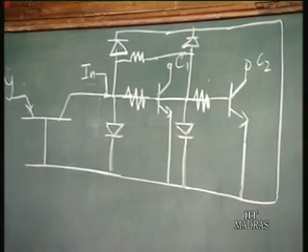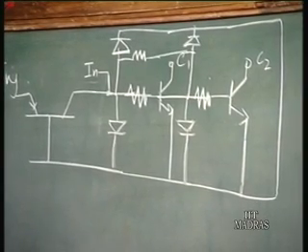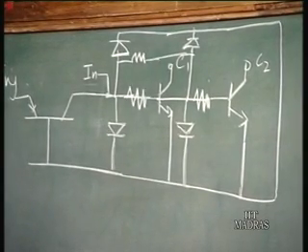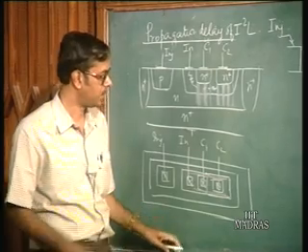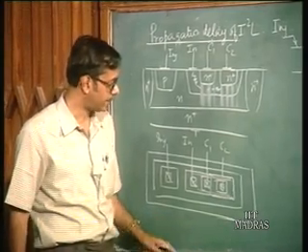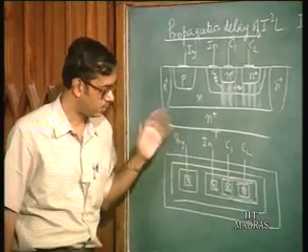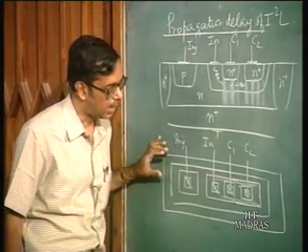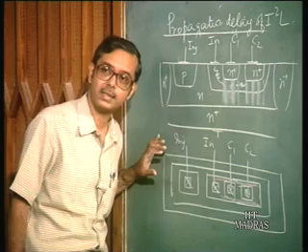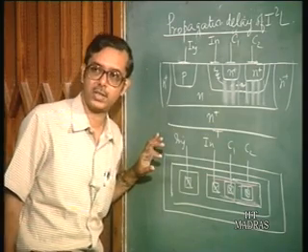So what do you do? We have to look at how to eliminate these parasitic elements. The first thing one can do came about with the proper isolation techniques, that is you use oxide isolation.